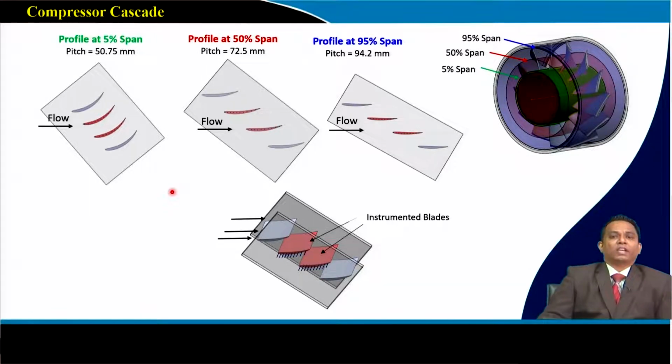During the initial stage of development of axial flow compressors and axial flow turbines, people did a whole lot of experimentation with different kinds of aerofoils. Some of them we have already discussed: subsonic aerofoils, transonic aerofoils, the C4 aerofoil, the NACA aerofoil, the CDA aerofoil, and the DC aerofoil. All those aerofoils were developed for a particular pressure rise, for a particular kind of CP distribution. So all this data is of great importance.